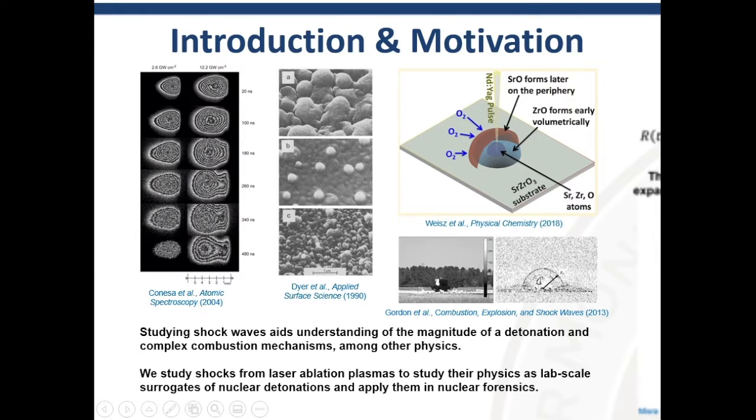These induced shockwaves carry a significant amount of information regarding the processes occurring during laser ablation, as studied by Kness and Gordon. The time evolution and geometry of these induced shockwaves are defined by the energy of the laser pulse and the shape of the generated plasma. This relationship of the shock wave and deposited energy motivates a need for characterization of these shock waves with improved fidelity, specifically of their spatial and temporal resolution.